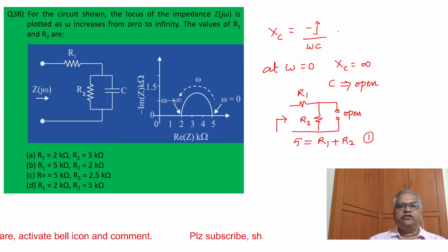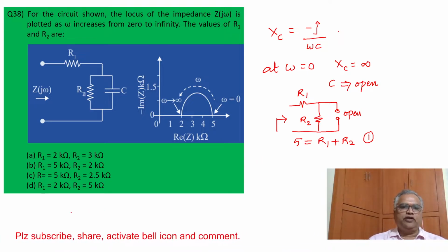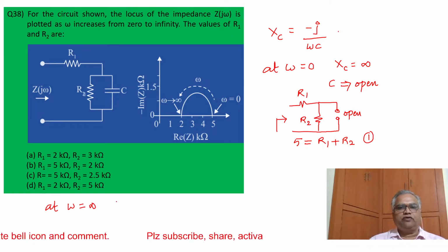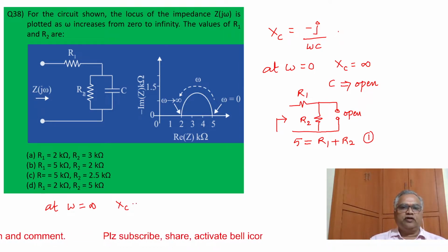Second, at infinite frequency, the impedance is given as 2. At omega equal to infinite, what is Xc? The capacitive reactance is 0, so the capacitor behaves like a short.